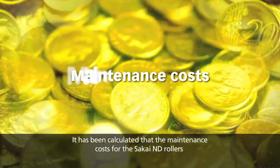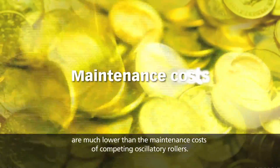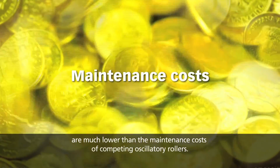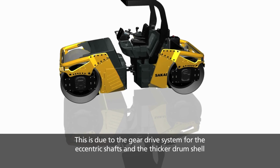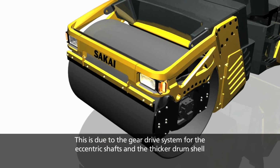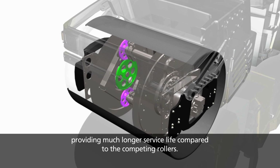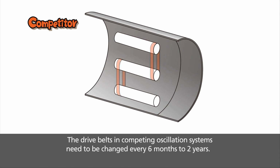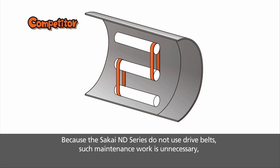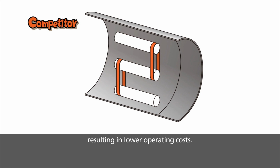It has been calculated that the maintenance costs for the SAKAI ND rollers are much lower than the maintenance costs of competing oscillatory rollers. This is due to the gear drive system for the eccentric shafts and the thicker drum shell providing much longer service life compared to the competing rollers. The drive belts in competing oscillation systems need to be changed every 6 months to 2 years. Because the SAKAI ND series do not use drive belts, such maintenance work is unnecessary, resulting in lower operating costs.